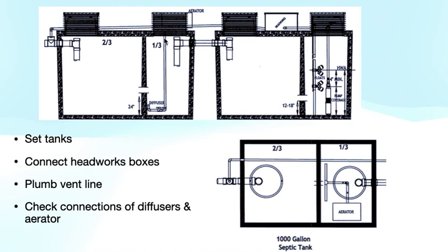It's all paired, and we provide adapters so that it's all 1-inch pipe here. This configuration down below here where I'm circling, where the diffusers will go, we're providing the diffusers, and we're providing a lot of this pre-manufactured along with a union up here in the riser to be able to pull that out conveniently and service the diffusers. So that's the aerator, and that's that initial first tank.